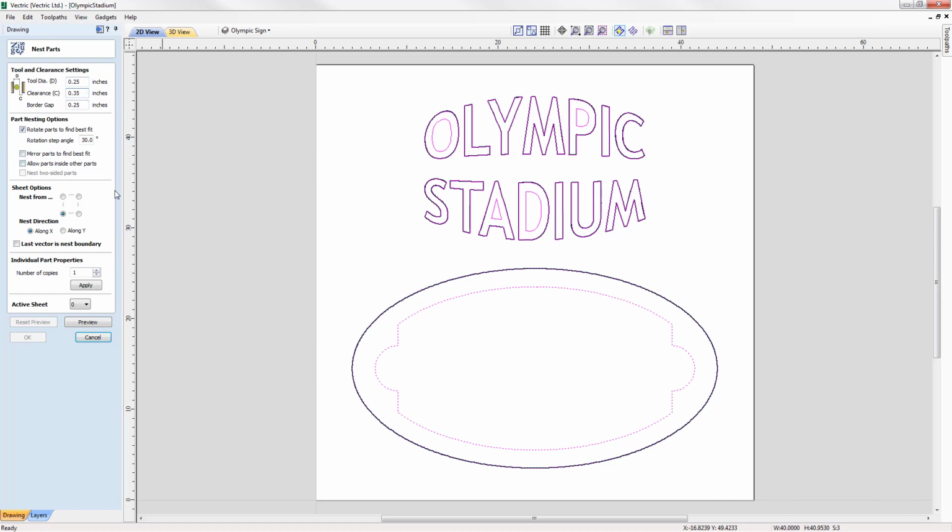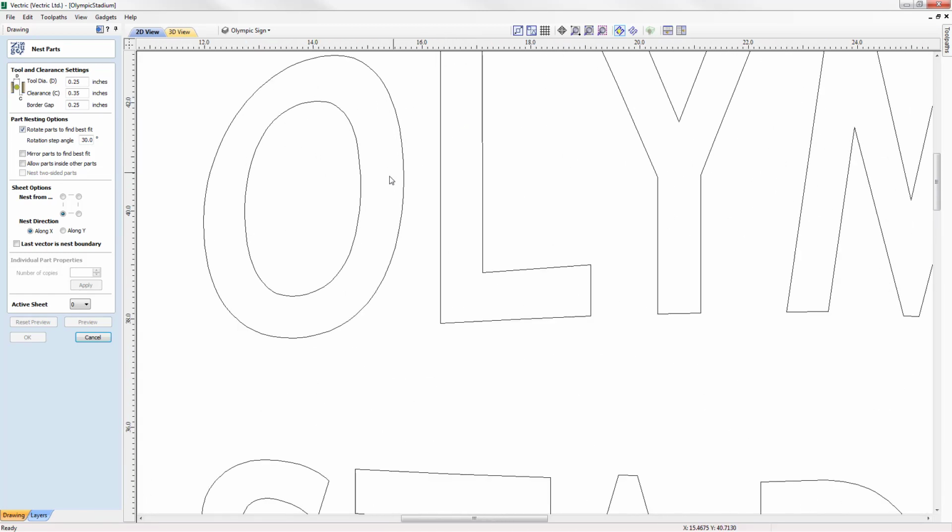And this would mean that for the minimum gap between any toolpaths that the tools may take, there'll be a minimum gap of 0.1 inch between each of those paths. And that will be built upon two lots of 1/4 inches on the outside. So imagine 1/4 inch on the outside of the O, 1/4 inch on the outside of the L, and then we would have a 0.1 gap in between them, which would build up to the 0.6 inch minimum clearance between the letters.